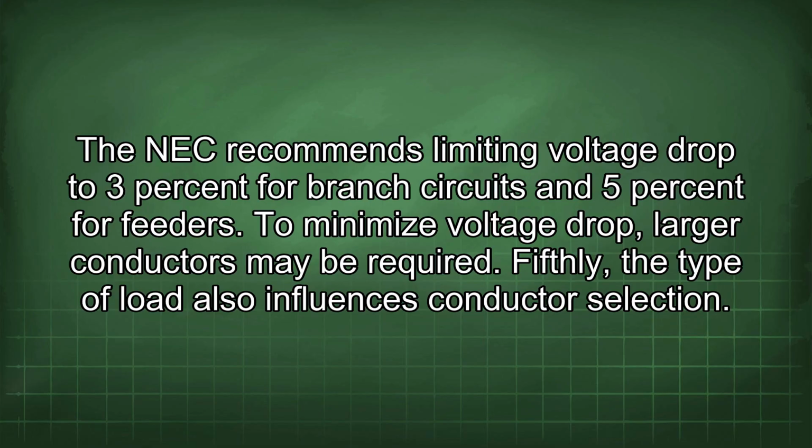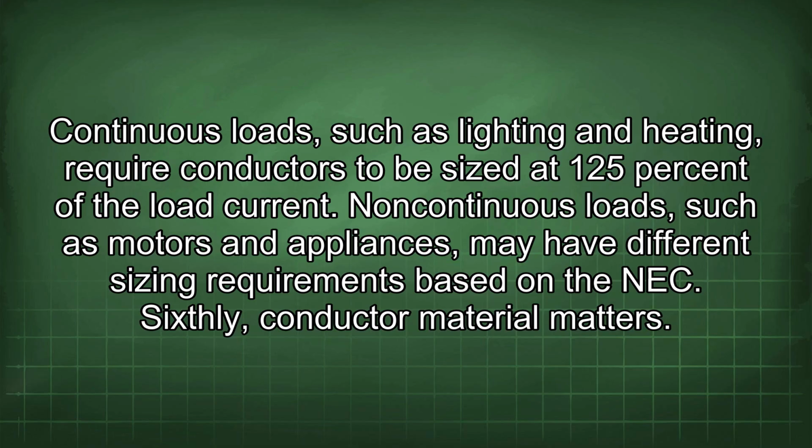Fifthly, the type of load also influences conductor selection. Continuous loads, such as lighting and heating, require conductors to be sized at 125% of the load current. Non-continuous loads, such as motors and appliances, may have different sizing requirements based on the NEC.